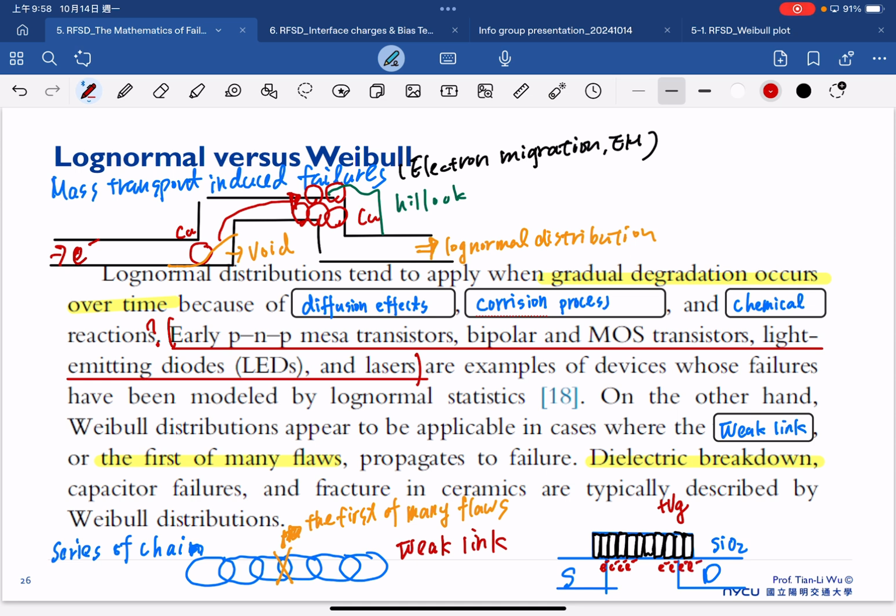However, if one of these small dielectrics is broken, for example here, then all of the current, all of the electrons, will immediately flow through this small broken dielectric region and become the leakage current. Because if you have already learned basic electronics, we all know the current will prefer to flow in the region that has a low resistance.